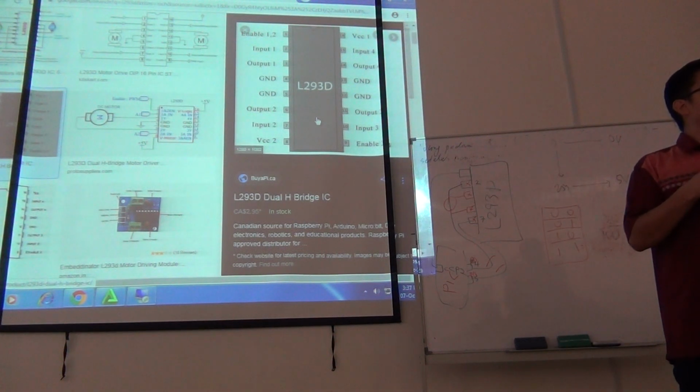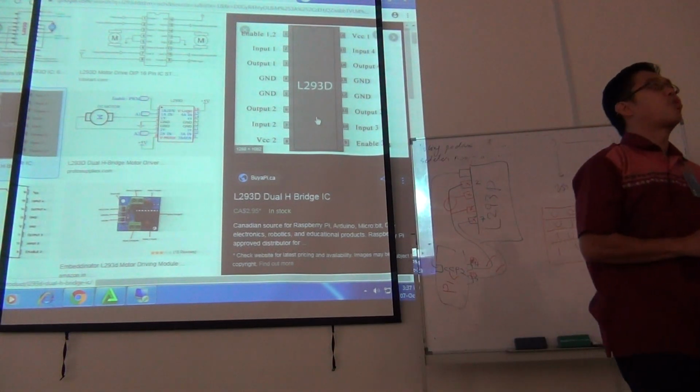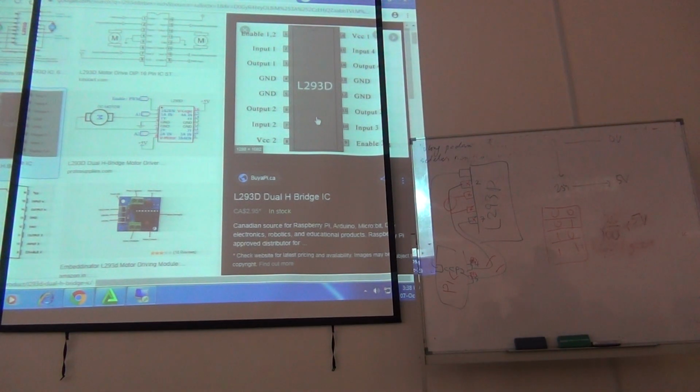You can only give directions, but you cannot control the speed because the speed is coming from the CCP pins. You cannot just simply put CCP pins talking to the motor because your motor has only two inputs, and those two inputs must be coming from the driver, which is going to describe its direction. So let's look at your L293D. This is the component and pin assignment.